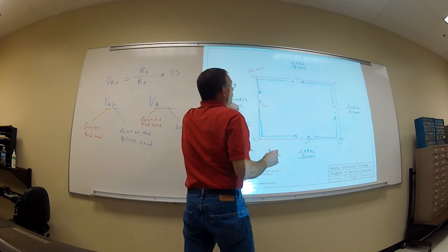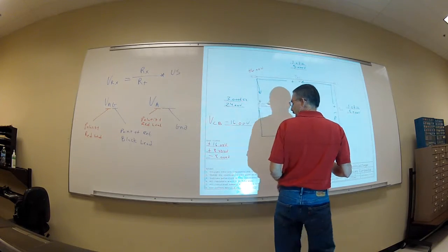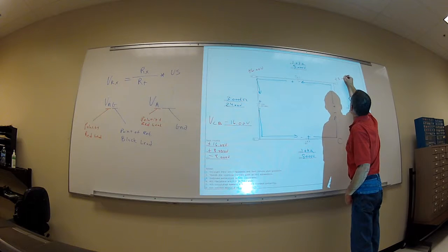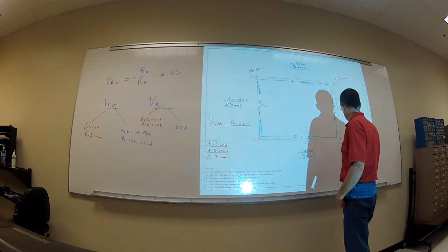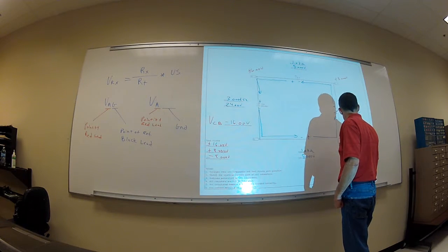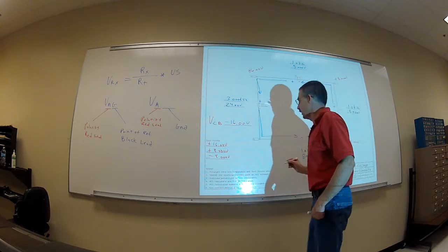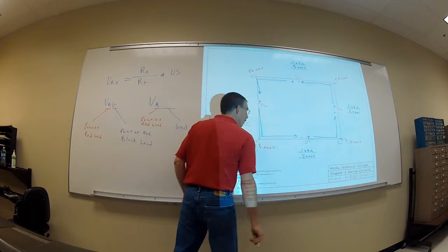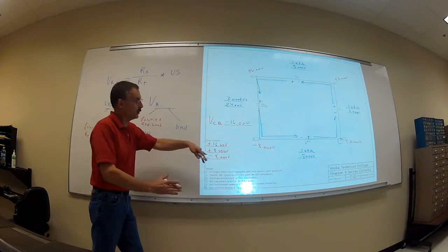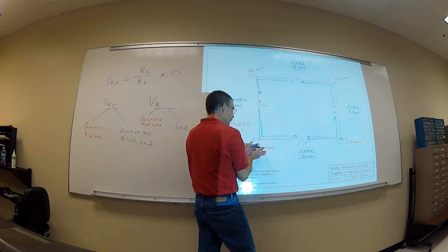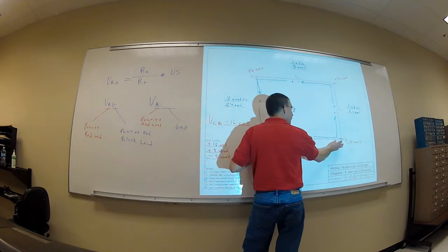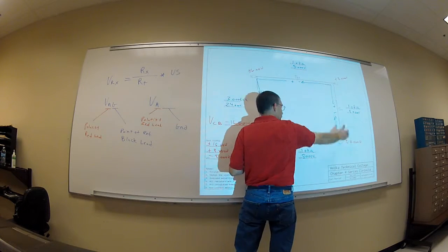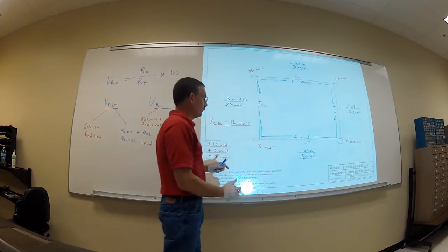So once we identify the individual test points, we have plus 16, plus 8 volts, G is going to be 0 volts, and C is a negative 8 volts, okay? Remember, it's with respect to ground. This is at test point C, with respect to ground. My black lead's on my point of reference. That's where all these voltages came from.